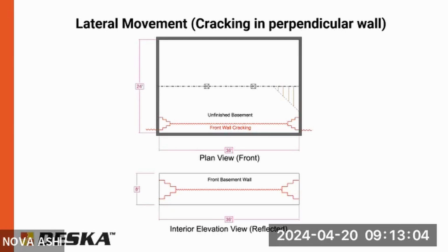Obviously, this can happen in a lot of different ways, but that's kind of the textbook look of that inward deflection. You can put a 4-foot level on it, and you can see how the wall is bowing inward. The 4-foot level will typically seesaw on the crack. Also, if you don't see a crack, sometimes you may just see that the mortar joint is a little bit thicker than the others, and that could be the sign that some repair has happened in the past. And so it's definitely something you'd want to look into.